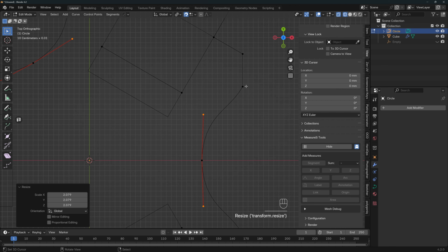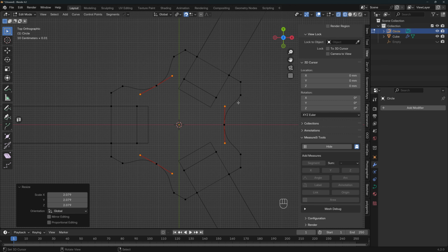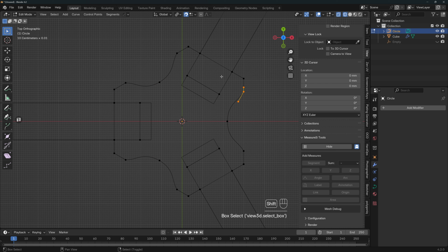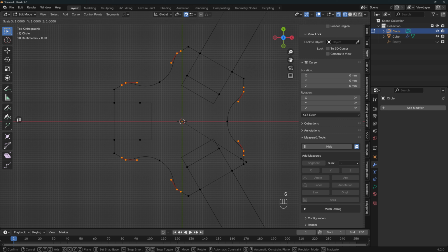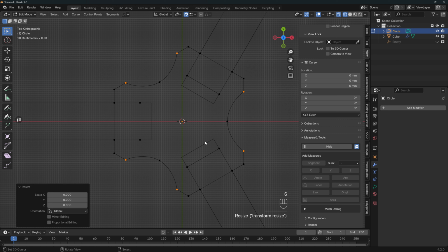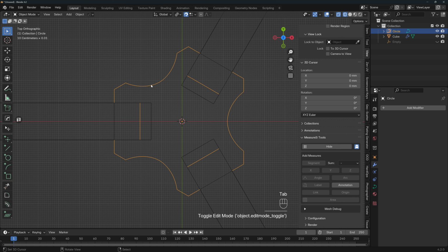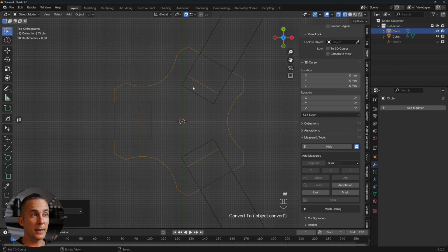And you can see right here it has some kind of a curve there. I don't want that, so I want to select this one and this one and this one, this one. I'm holding Shift, this one and this one, and go back to individual, right, S and 0, and you're done. So now if you go back to object, this is how it looks. Really, really nice. I really like it. We can go back to the object and right click and convert back to mesh. This is what we want. Then go back to edit.